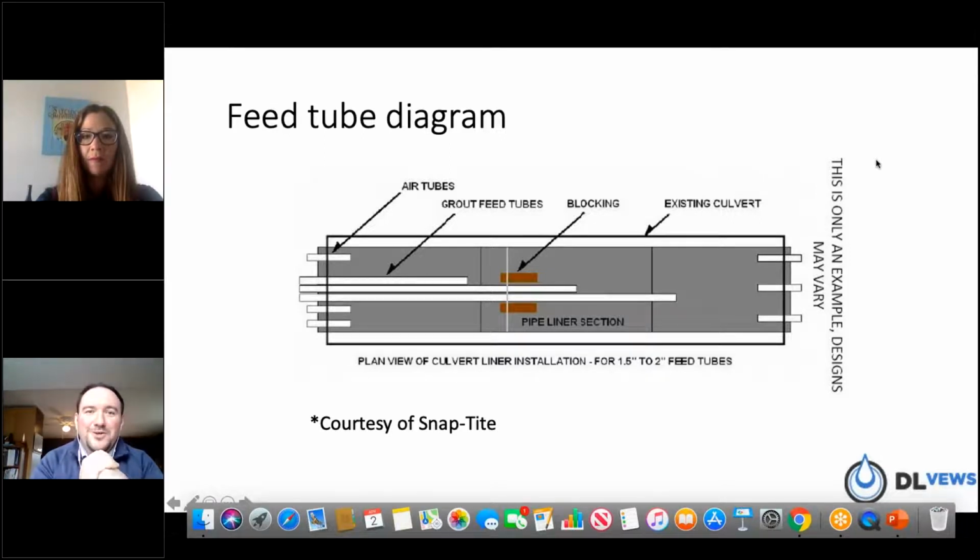Right. And so, some of these pipes that are steep, we deal with a bunch with Pennsylvania DOT, out near Pittsburgh and Cranberry area, where underneath those highways, there's this crazy amount of pitch. Also in the Finger Lakes region in New York and wine country, those pipes start high and end up really low at the outlet. So we've got to be cautious, or at least cognizant, of what is going on with the grout there. So I'd say 5 or 6 maybe might be my most amount of groutless that I've experienced personally. Could be even more.